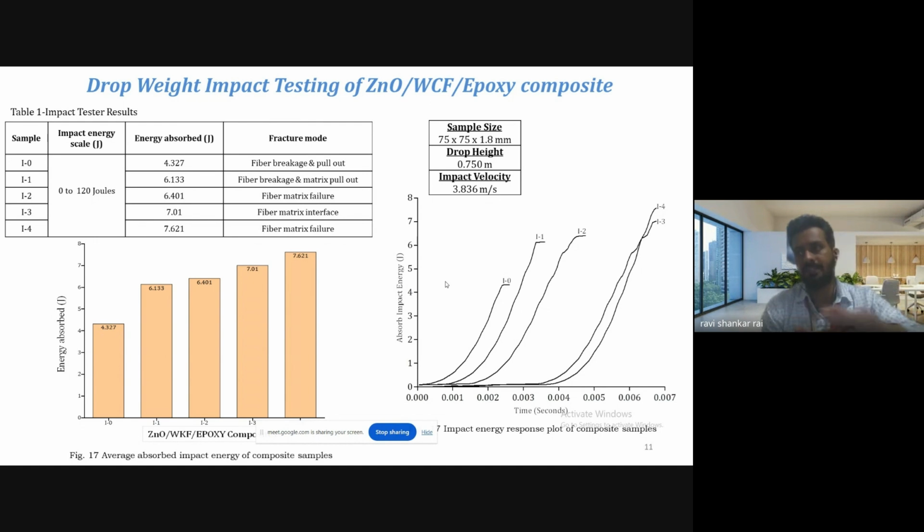After that, we stacked them together and used a polymer matrix, which is a bisphenol A epoxy resin. We applied vacuum-assisted resin transfer molding to make the composite material with low porosity, or low defects. After preparing the samples, we categorized them into five categories: one having no nanostructure and four having different molar concentrations.